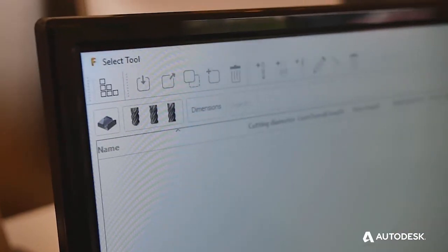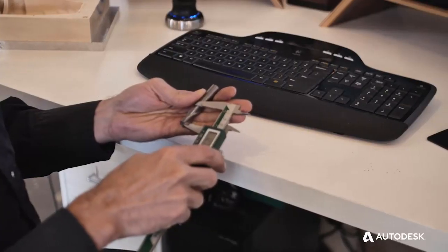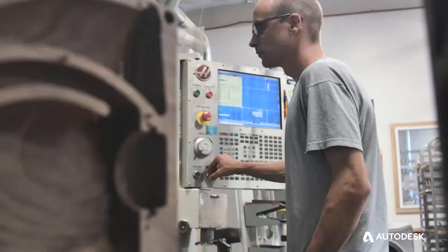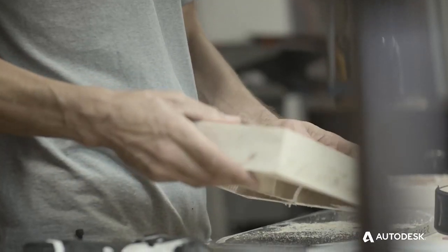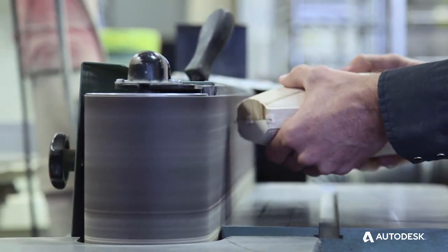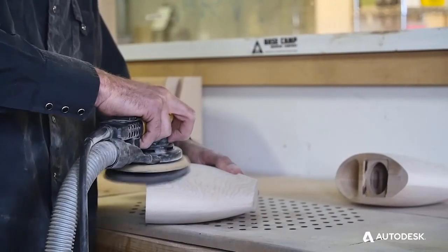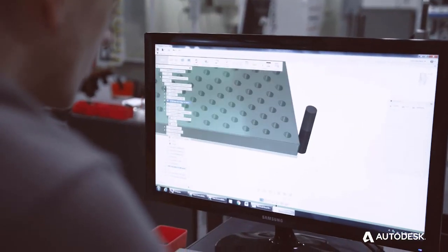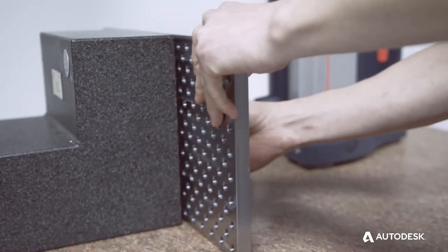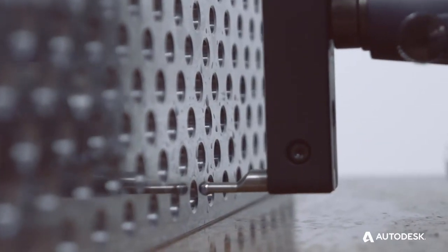In addition to capable CNC machines, the quality of the toolpaths the CAM kernel generates is important to manufacturing success. Traditionally, toolpaths were simply offset passes calculated using the constant step down and step over parameters. These toolpaths are reliable, but increased forces on the tool in internal corners often lead to breakage without precautions like reduced feed rates. Constant engagement roughing toolpaths, like Autodesk's adaptive clearing, use algorithms to keep a constant engagement on the tool, effectively keeping a constant load on the tool and allowing faster and deeper cuts than the traditional toolpaths.